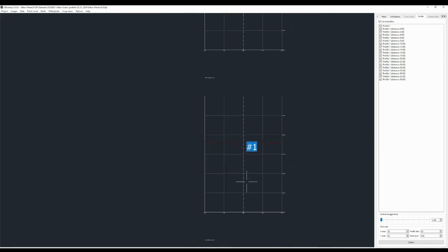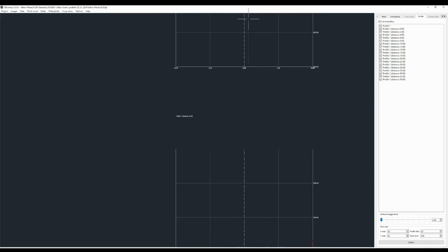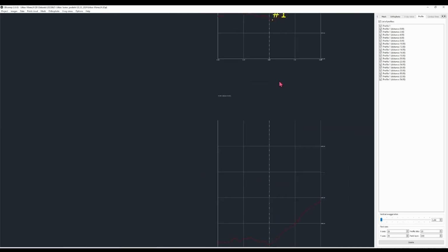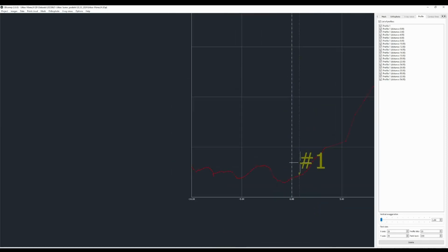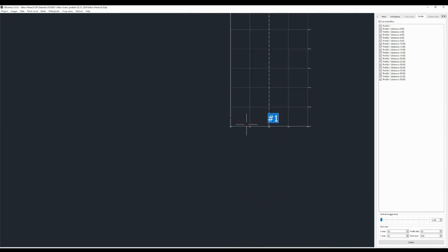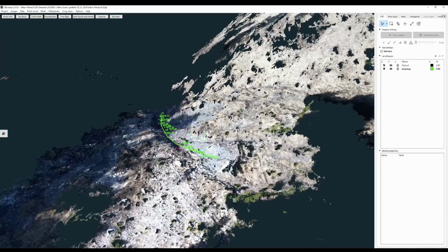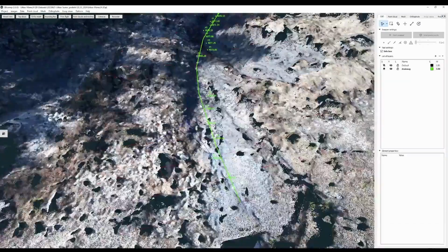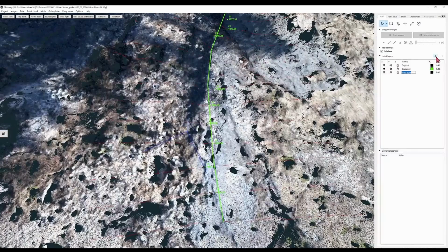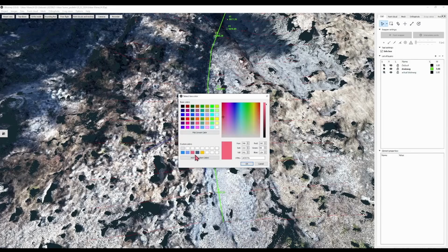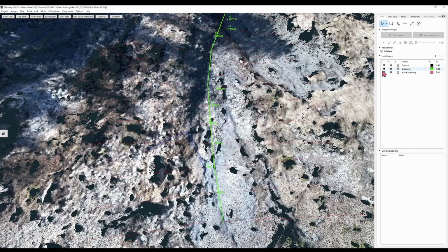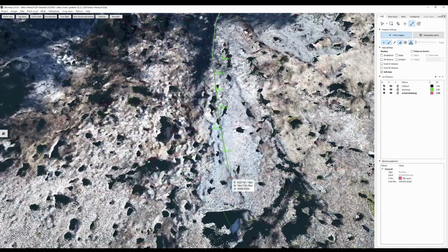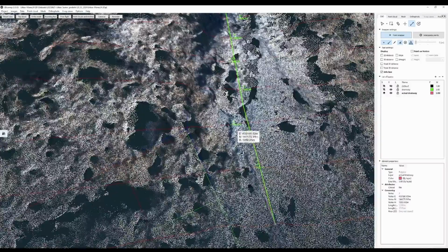And as we go through, we can check if we picked the correct spot, meaning that the center line is aligned with the lowest point. And as we check those perpendicular profile lines, we place a point on each one of them. And we go back into the CAD, and now we can see where we were off. So what we can do now is just connect those points that we created in the profile tool, and we'll have the correct lowest point path downhill.